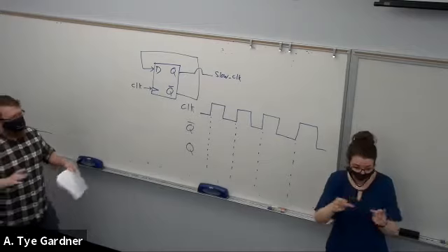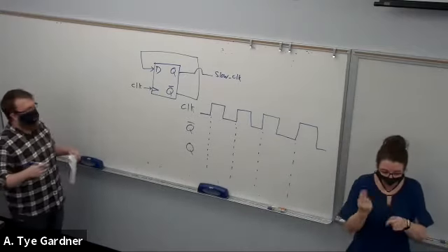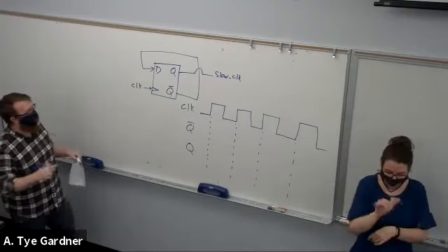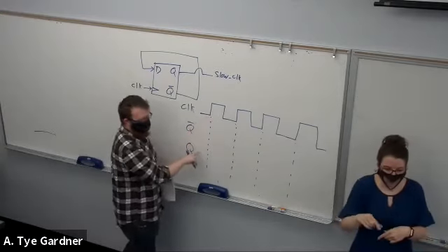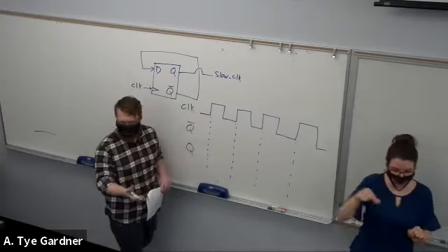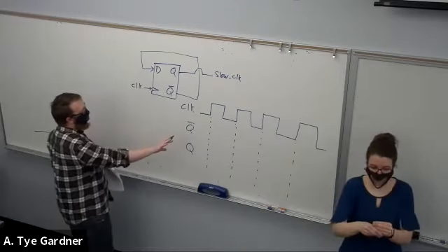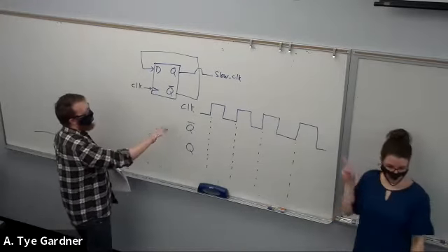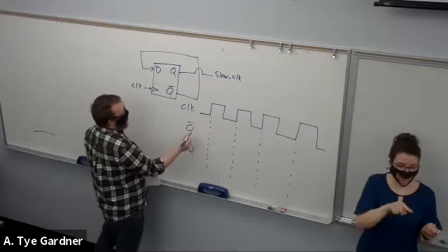Now, the exception is if we bring in those delays that I talked about last time, which are things like clock to Q. What is the delay between the rising edge of the clock and when Q updates? That's one type of delay that we mentioned. We'll get into more detail on delay in just a minute, but let's start here.